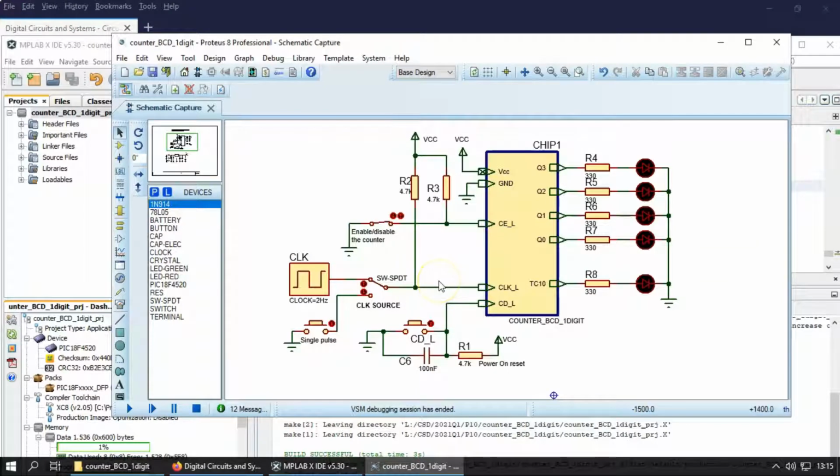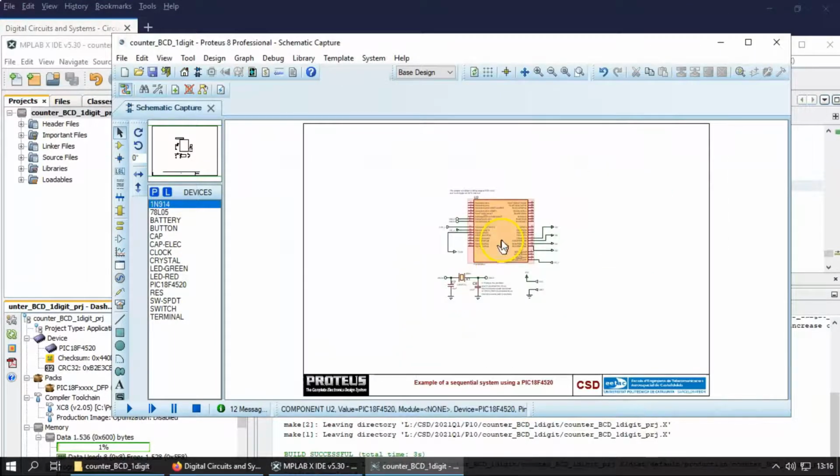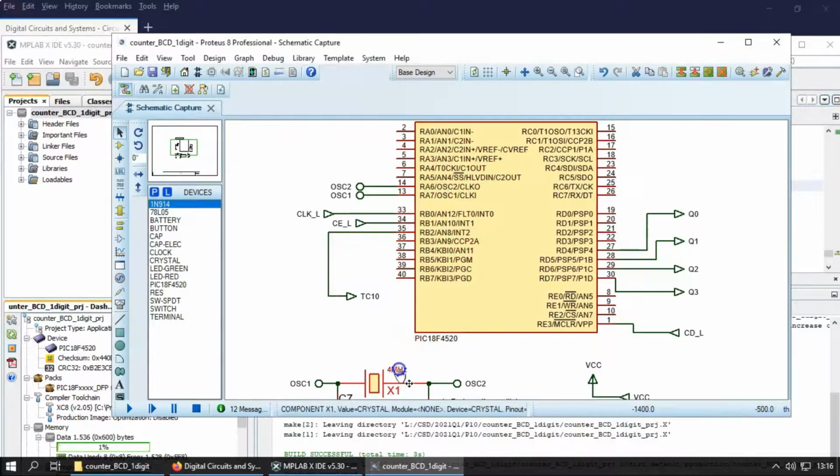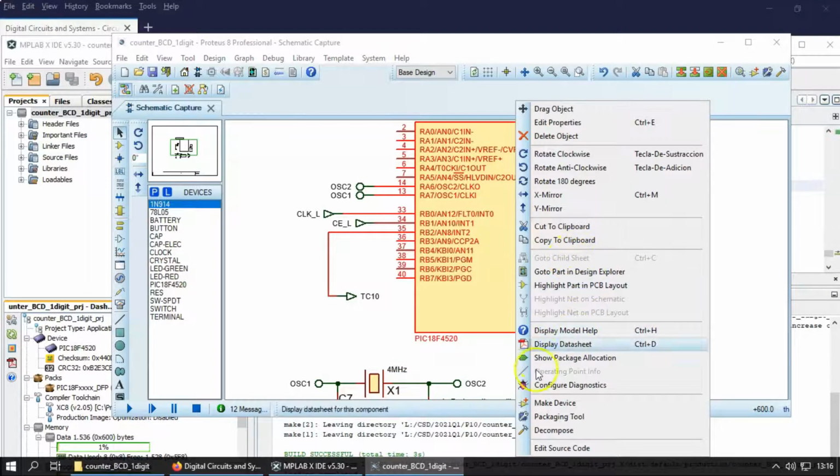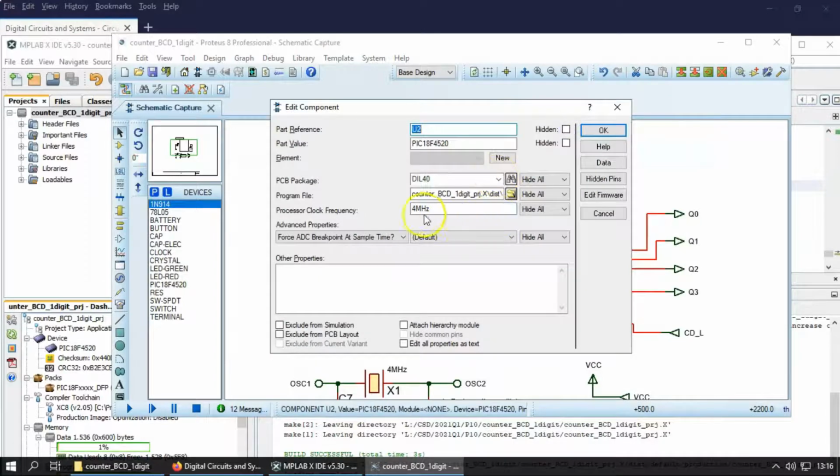And you know that you can make that loop larger, introducing more instructions, or shorter, optimizing the code, or whatever. And you know that you can execute this loop 4 times faster by going to the computer, stopping the simulation, and setting, not the picture, right? The picture doesn't matter because it's a simulator. So the value that has interest here is the clock. So if now the clock is 16 megahertz instead, you have to execute the same number of instructions, right? But 4 times faster.